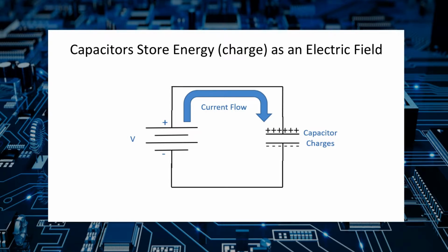Once the capacitor reaches its final fully charged value, which is equal to the voltage applied across the capacitor, then the capacitor is fully charged, and the voltage and the current stop changing. At this point, the voltage and current stay the same. They remain steady, and that's why we call it the steady state.